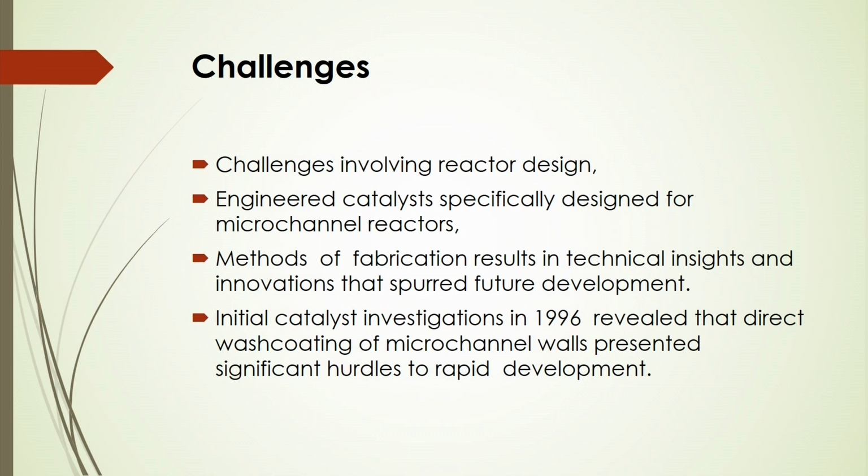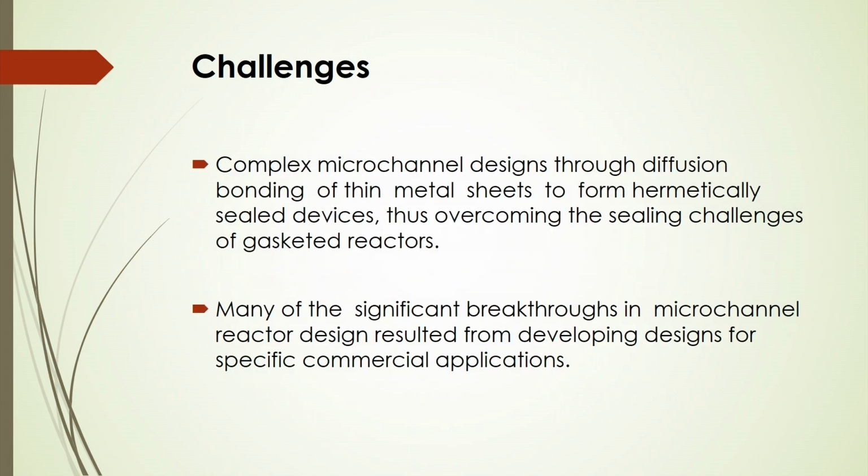Initial catalyst investigations in 1996 revealed that direct wash coating of microchannels presented significant hurdles to rapid development. Many of the significant breakthroughs in microchannel reactor design resulted from developing designs for specific commercial applications.